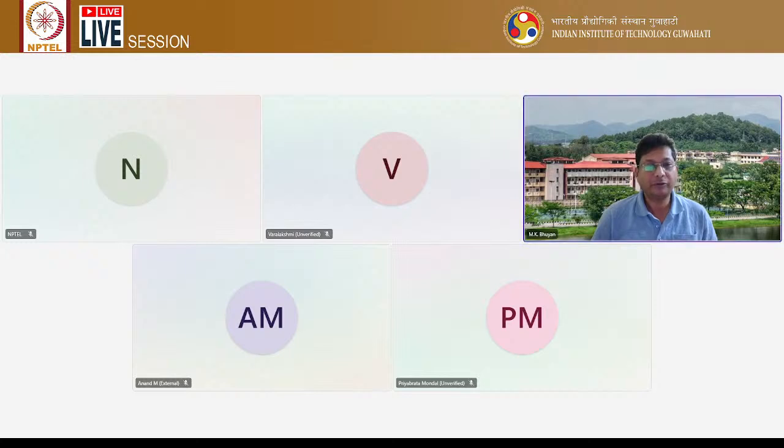In week number 5, also the same concept, image transformation, we discussed the DCT and wavelet transformation. So that you have to understand. And after this, we also discussed image enhancement in week number 5. So how to improve the visual quality of the image, how to remove noise, the concept of contrast enhancement, the histogram equalization technique, and the histogram specification technique.